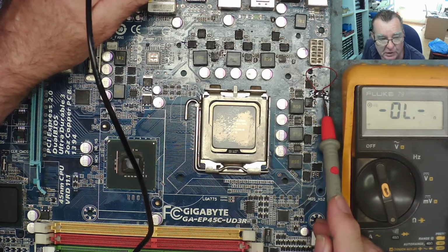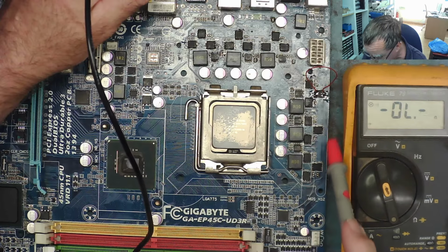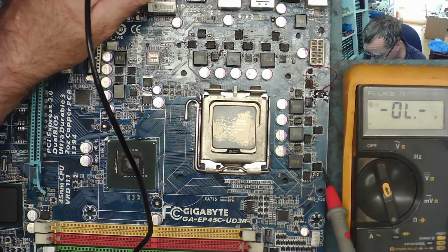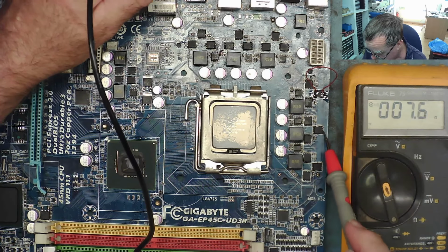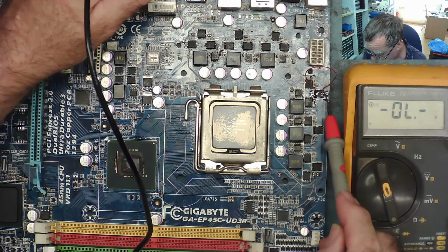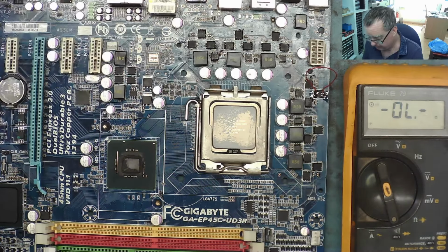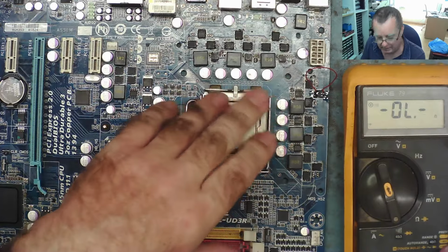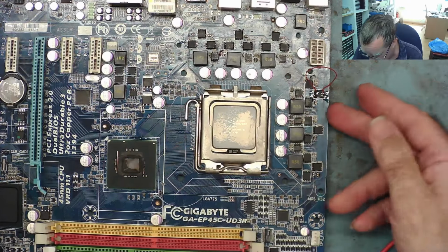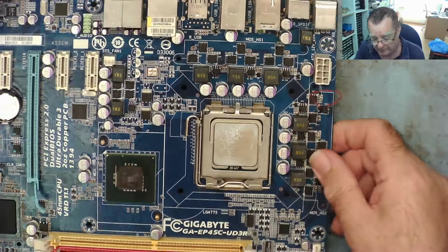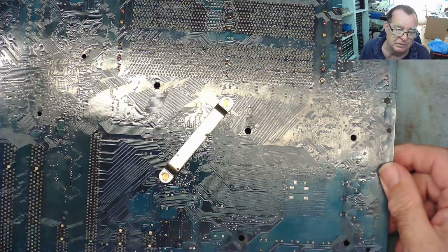If we go to the short circuit I've put on here, you can see it, yeah? But if we go to the other MOSFETs, the short is everywhere, and we can't see a difference between the reading on any of them, yeah? They all read the same. So how can we find the short? Well, one very good way to do it is to use the ESR meter.